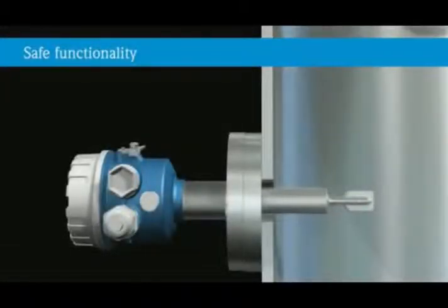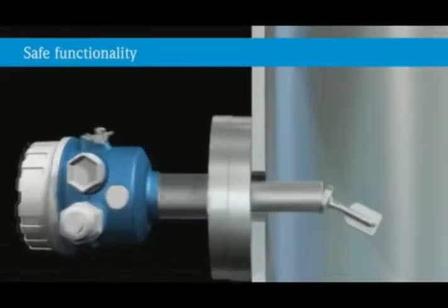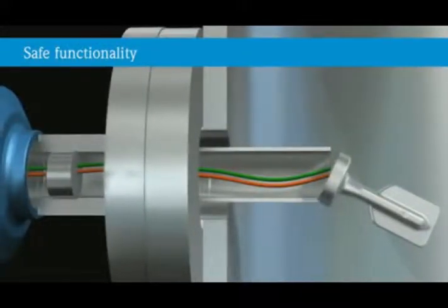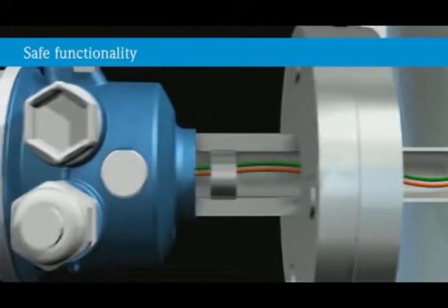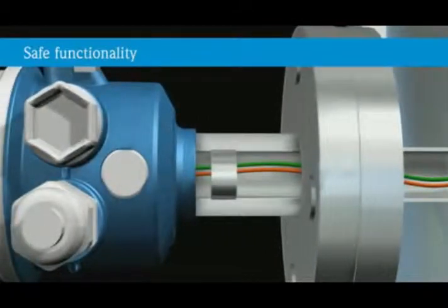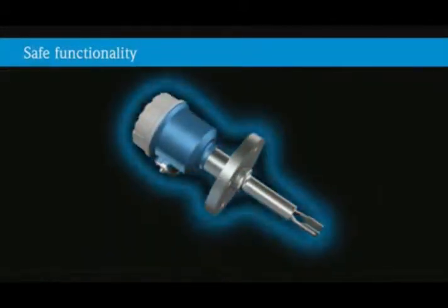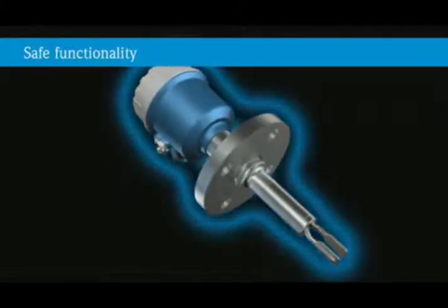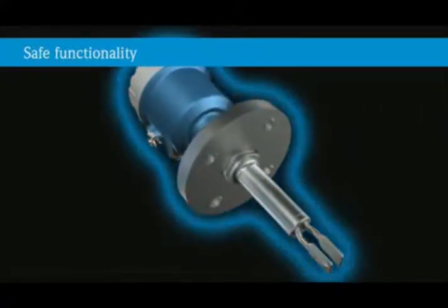If mechanical damage occurs on the process side, the second line of defense takes over. A pressure, gas, or diffusion tight feed-through reliably prevents the medium from escaping into the atmosphere in case of a failure. Liquiphant permanently monitors the oscillation frequency, thus providing a reliable early warning system in case of malfunctioning.